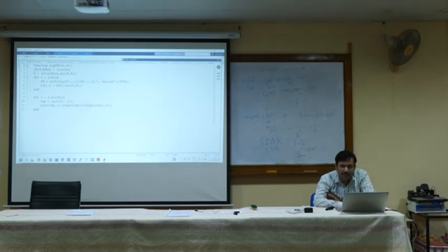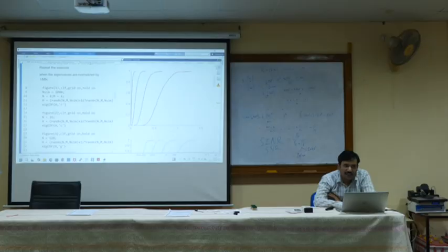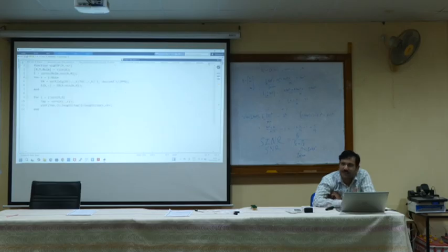So H is what? I am generating 1000 channel realizations. So N sim is 1000, and N cross M matrices. So this is a 3-dimension matrix, and the third dimension is 1000. That way I will have 1000 matrices in one go. Otherwise, what can I do? I can do a for loop and generate the matrix again and again. It will take more time. So I have generated all 1000 matrices in one variable.